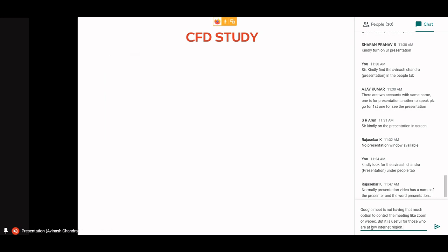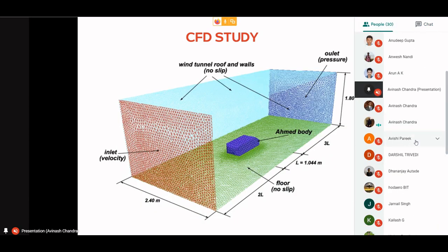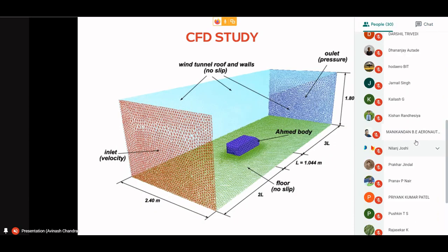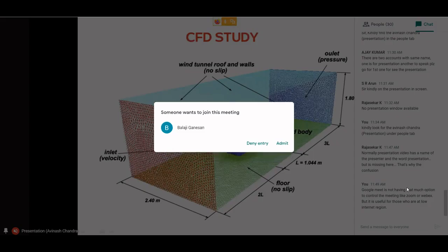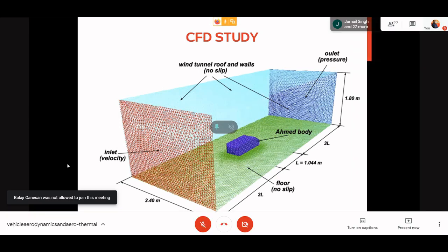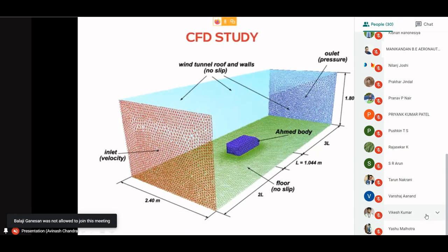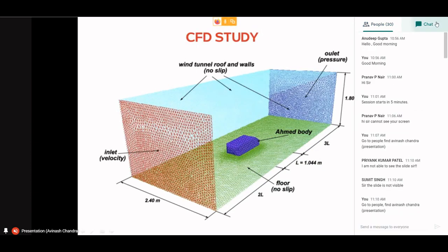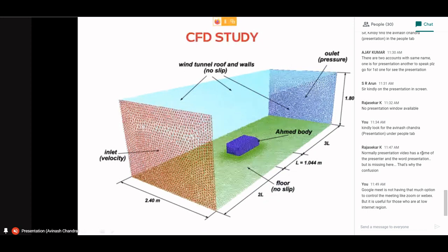Now, what is slip boundary and wall boundary? Slip boundary is basically you are saying there is no friction on the body. There is no friction on the object. So if we take the upper section, a rectangle, and I define a slip condition, there will not be any kind of boundary layer generation from the top part. So whatever is your free stream velocity will be the velocity at this rectangle or at the plate.